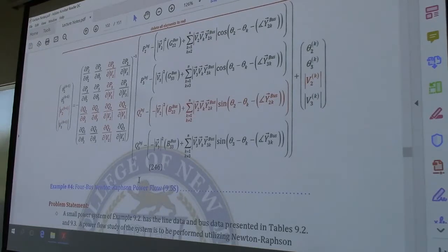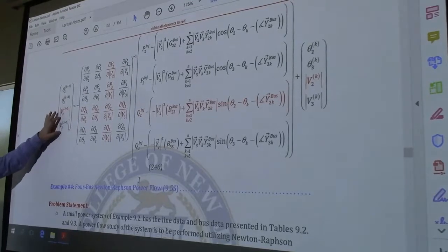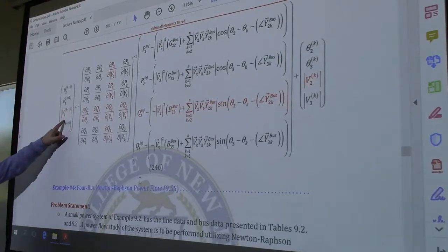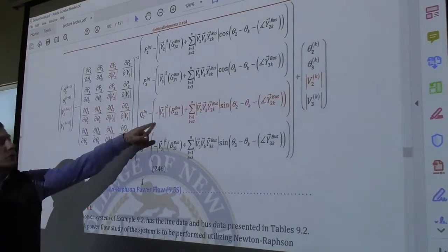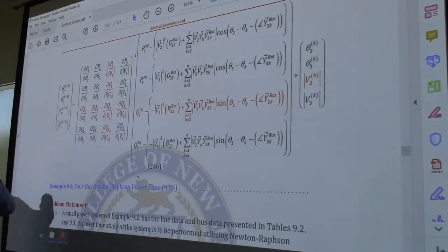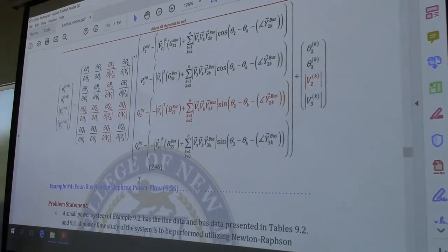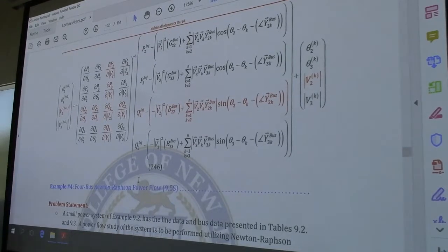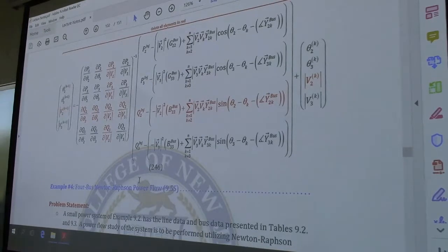And so actually here's an example of eliminating it. And here's a more reasonably sized example. Now you can see when you start to reduce it down to the sizes that we're going to be working with, it doesn't look as bad. So this is an example of a 3-bus system, 2 non-infinite buses. Our bus number 2 in this case is the PV bus. And so that goes away, and that goes away, and you just collapse the whole thing, and you end up with a 3 by 3. And so hopefully now that doesn't seem as bad as it would be otherwise.